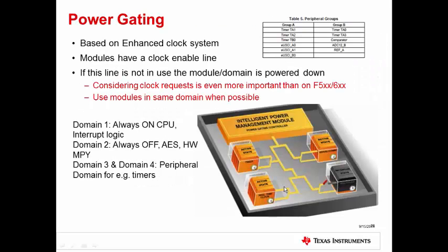To reduce wake-up losses, FR59XX uses power gating. Only modules that are requesting a clock are kept powered, but modules that are idle are only powered at retention levels, meaning that only logic specific to retaining the state of the module is powered. This helps minimize wake-up losses.